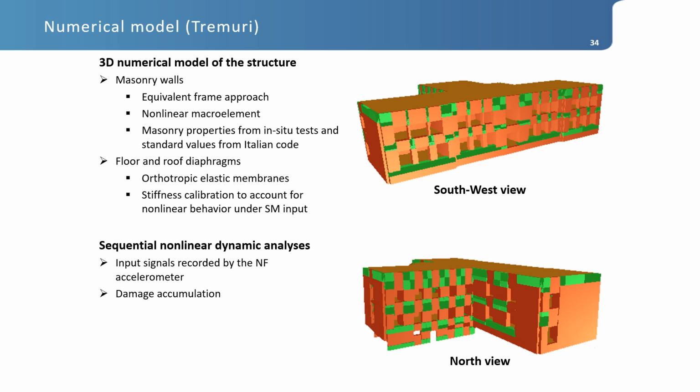And we also calibrated the stiffness of the system to account for the nonlinear behavior under the strong motion input. This small calibration was actually based on the initial recordings that were performed in the dynamic identification of the structure.